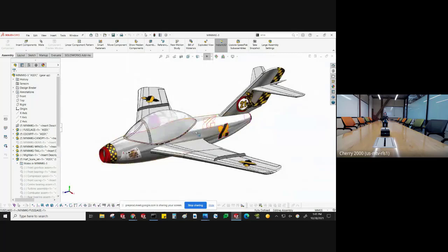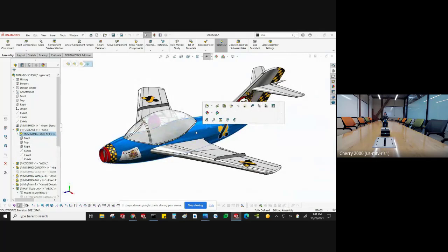So here we go. This has got a little bit more to it. You see that when I select on something, it's got these feathers in front of it. And those are what's known as lightweight parts. So all I'm looking at is basically, again, the tessellated data, the e-drawing, just the skin of my model. It doesn't see it as a solid. I don't get any access to features. I can just see this reference geometry. If I want to mate things to an axis or a plane, I can get that and use my mate tools in this lightweight mode.